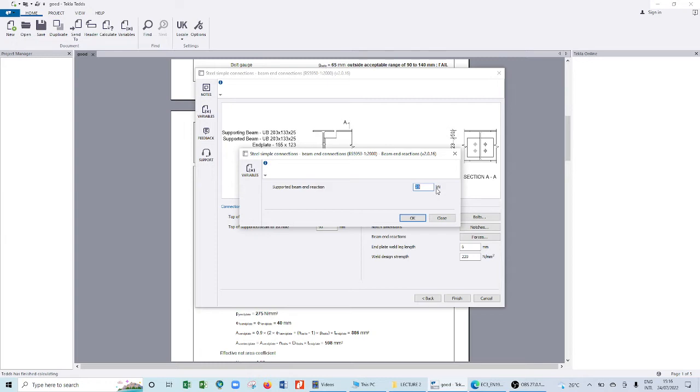Maybe the finishes, I've done them. The section is given per meter. That's why you find the running weight: UB 203 by 133 by 25 kg per meter. So when you get its weight, you get the total length times that per meter value. That's why we have 25 times 3.12, which is the length. What we are getting is kilograms times gravity to convert it to newtons, then we divide by 1000 to convert it to kilonewton.